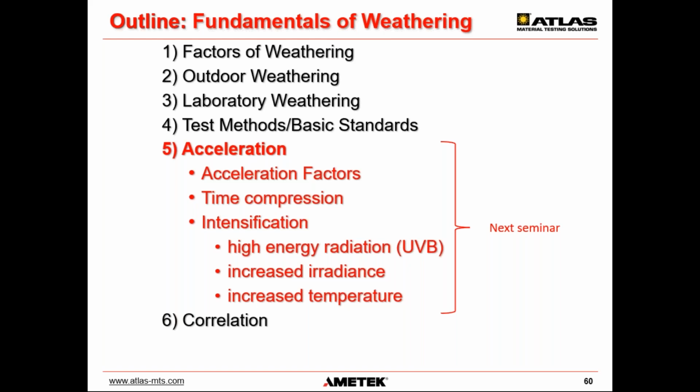If you look at ISO 4892-3, which is specifically for polymers, it will give you some guidance on which lamps to select for the different applications. It's actually a pretty useful tool in developing a specific set of requirements for your product.